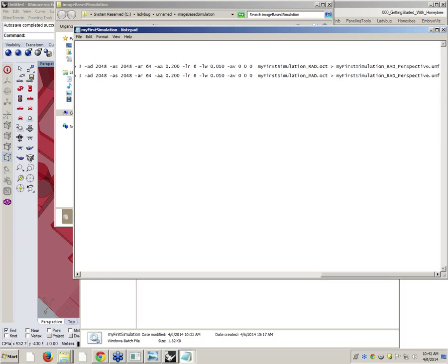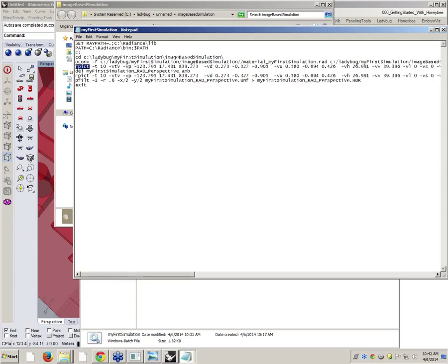And then I delete that. I delete my ambient file. And then I run it again. Run the rendering again. And when I'm done, I just do a size change here. This is again something in Radiance. You just render it bigger and then you change the size to have a better quality image. If you want to read about this, go to the manual of RPict.